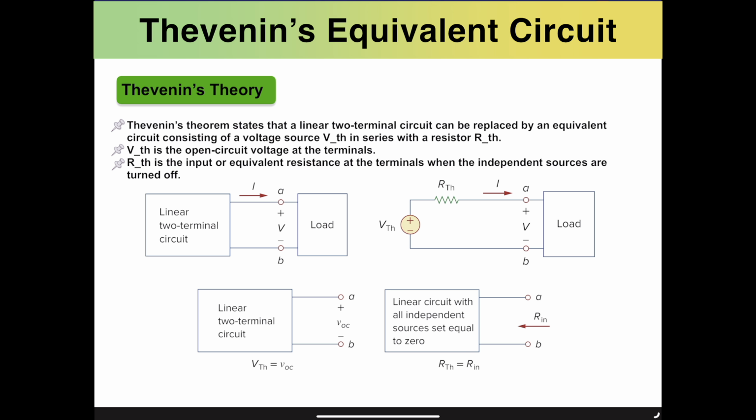In this process, we will need to break it down into two pieces. First, we need to find the voltage of the Thevenin equivalent circuit. That will simply be the open circuit voltage, which means that we keep all of the current sources and voltage sources of the initial circuit, and we just need to find the open circuit voltage across the terminals of interest.